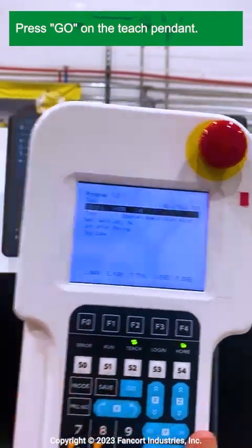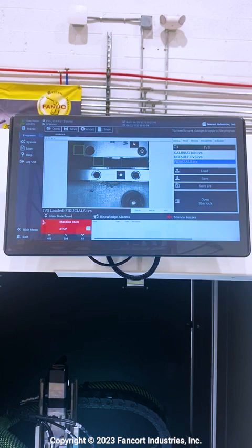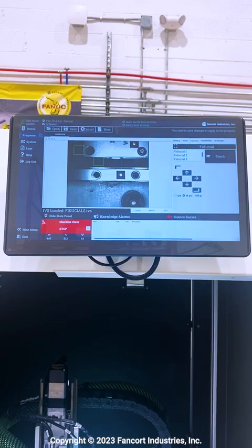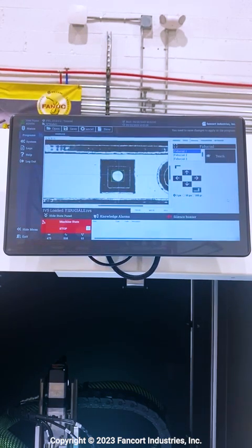Go to P1, go to the FIDUCIAL tab and select FIDUCIAL 1 and tightly surround the FIDUCIAL mark. Tightly surround FIDUCIAL 1 and select Teach. If you have any errors, reference the manual. The mark should get larger and turn red.